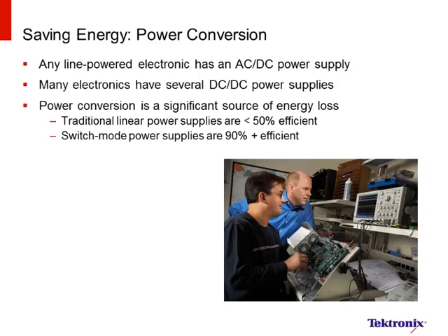Today, switch mode techniques are used for power conversion. They offer efficiencies of 90% or more by minimizing the use of lossy components such as resistors and linear mode transistors, and instead using components that are ideally lossless. Validating and characterizing switch mode power supplies often requires measuring switching loss and magnetic power loss to help optimize the efficiency of the converter. We'll further discuss these topics in the following slides.